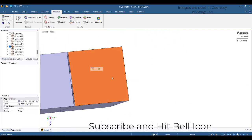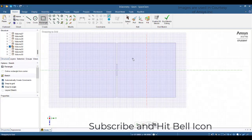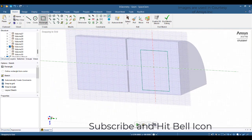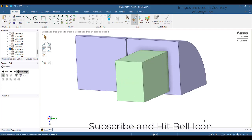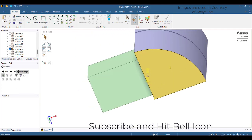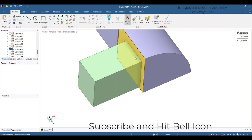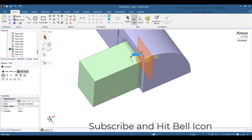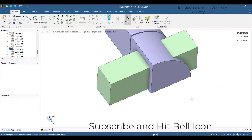to just select this, go to sketch, select some rectangle, try to draw some rectangle, right? Now come out of this extension mode, select no merge option, this one, this side, similar with the other part of it also, and just select this face, no merge, this side, right? So now we've got a different body altogether.